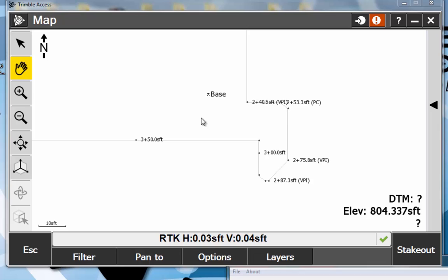Can you see that line okay? Something look a little off there? Curves. It ignores the curves, right? So I have my alignment. I can stake this station and offset, but when I do it in General Survey as an alignment or as an RXL, I lose all my curve information. So how do I stake along that curve radius in here? Any ideas? Probably can't, right?